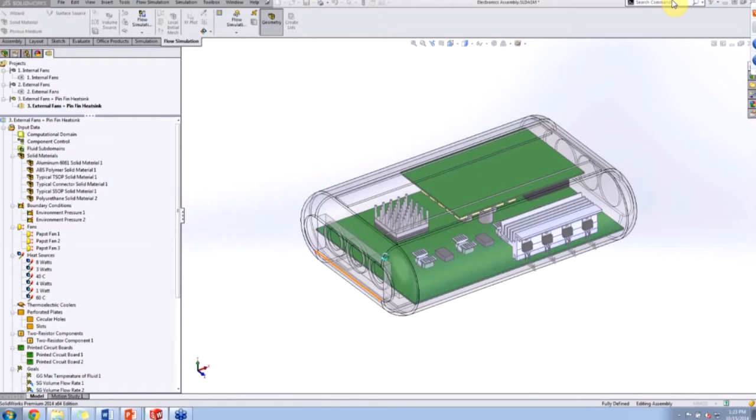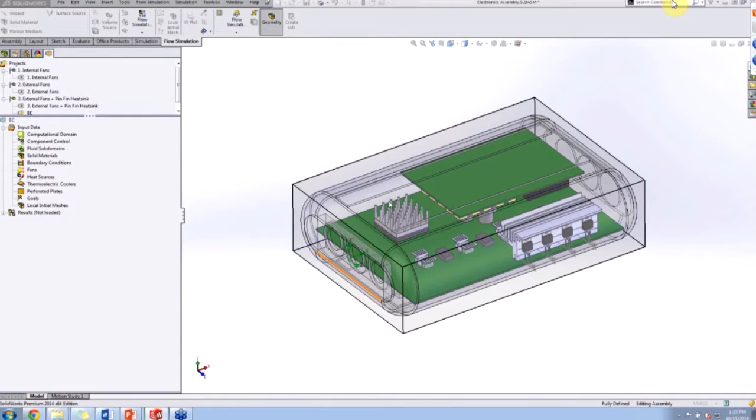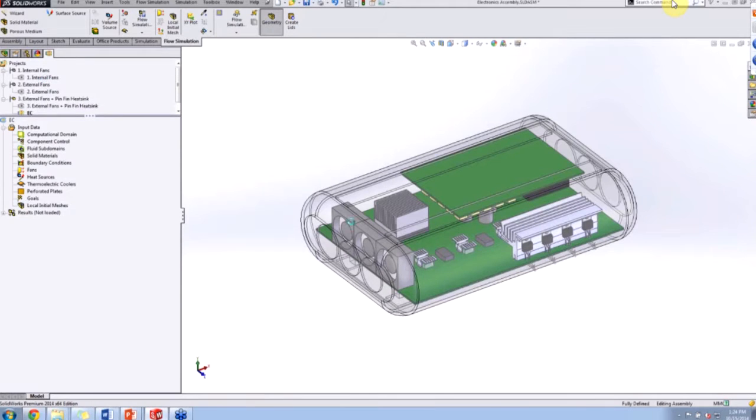And that's it. We just specified this was step 1 as far as creating that project. We gave it all the internal conditions that we want. Now we have to specify the boundary conditions, right? So instead of me setting up this problem from scratch, I do have a scenario here where I want to run internal fans within this enclosure. I already have it pre-set up here, and I'll just run through the general boundary conditions that we have here. So let me load it up.